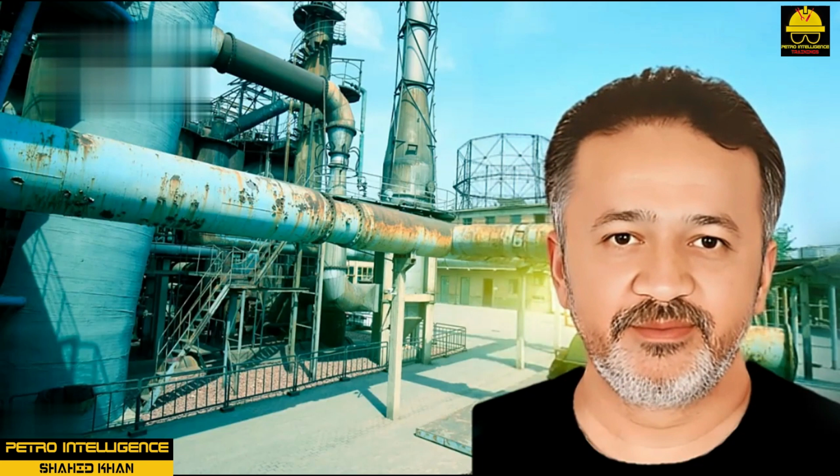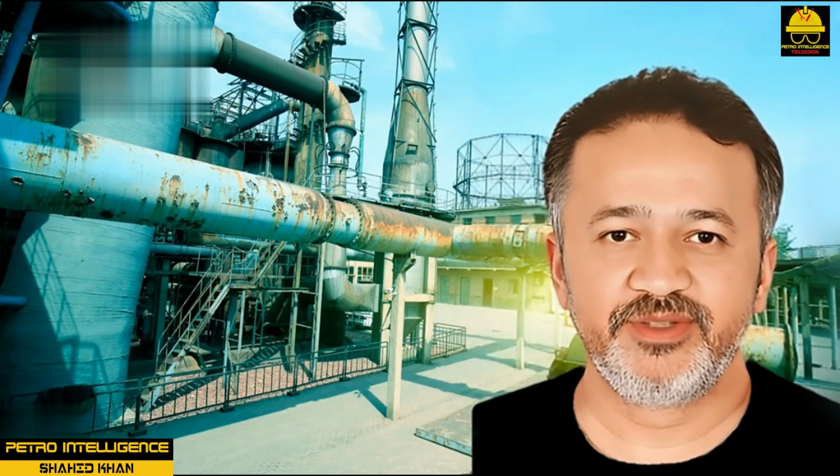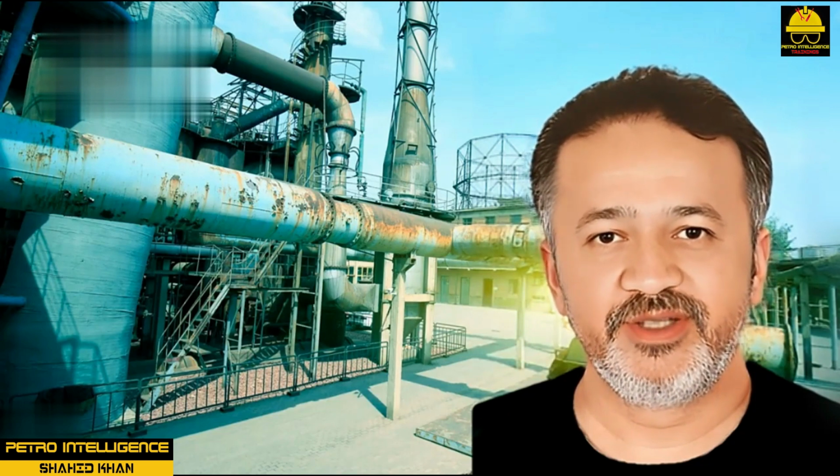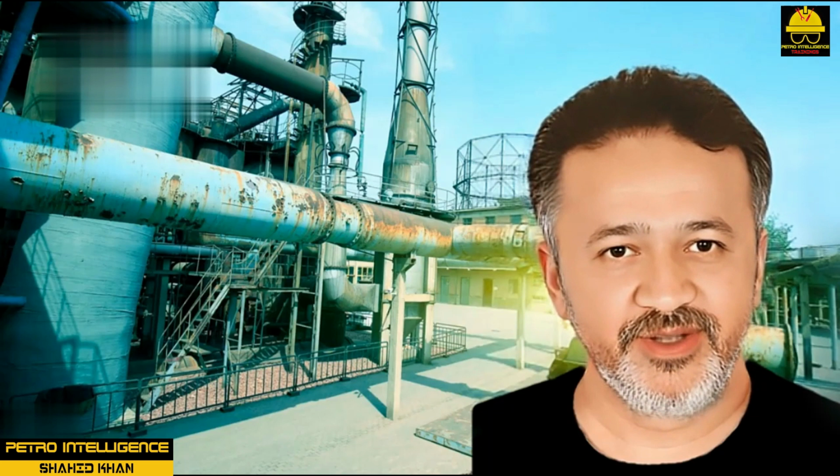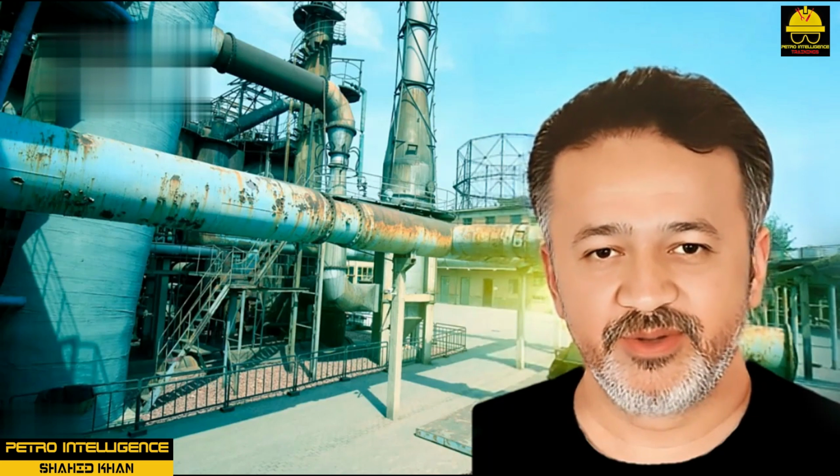Cold relief system, cold flare. The cold relief system collects liquids and vapors below 32 degrees Fahrenheit or 0 degrees Celsius after expansion into the header. It is important for operators to recognize that, although the cold flare system is designed for extremely cold temperatures, there are portions of some connections to the flare that have a higher temperature specification than the cold flare system itself.